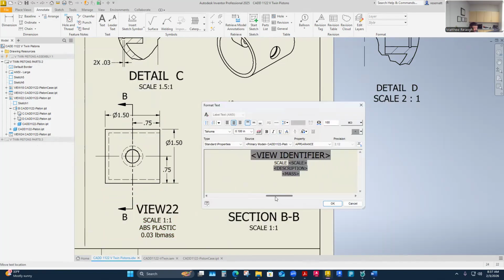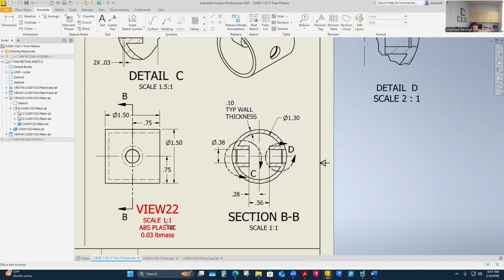This isn't what I'd want to do. I'd like my template to be fixed, but what I'm going to do is highlight this word. That's 2.4. That's the correct size. ASME likes a 0.24 large, they call it a large style text for view labels. And then underneath it should be 0.125 as ASME standard. And these are kind of mixed, maybe it looks, but they should be 0.125. I think they are. I just don't think it's showing up that they are.